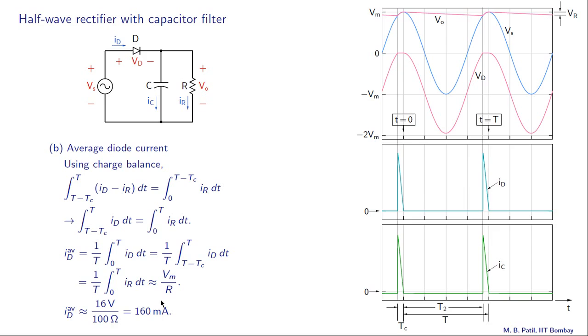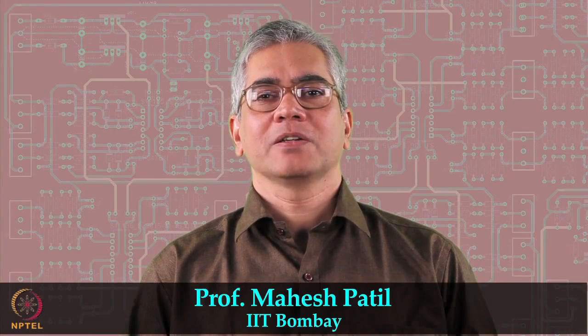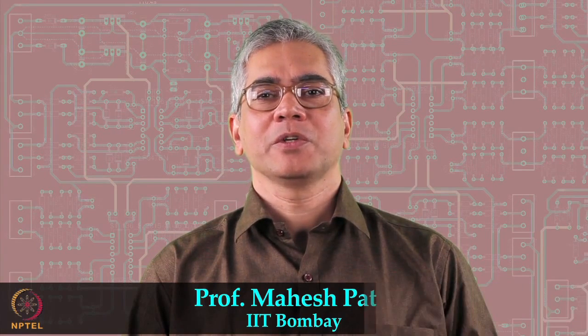And for this example, it turns out to be 16 volts by 100 ohms, that is R, and that is 160 milliamperes. To summarize, we have used an animation based on the analogy between the half wave rectifier and a hydraulic system. This analogy helped us to identify the factors responsible for a non-zero ripple voltage at the output. After that, we worked out an approximate formula for the ripple voltage and used it in a numerical example.